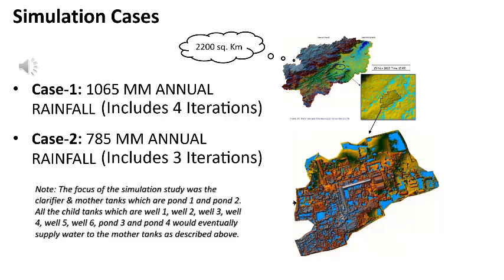In the first part, a watershed was computed through GIS techniques for the region, and it indicated 2200 square kilometers as the observation area. The significance of this watershed was that all the rain that falls in these areas shall typically be trapped in the area itself. Therefore, either it will be absorbed in the earth or remain stored to create a flood-like situation. In the planar region, with a range of hills and mountains on the northern and the western sides, the risk of flooding remains a concern.